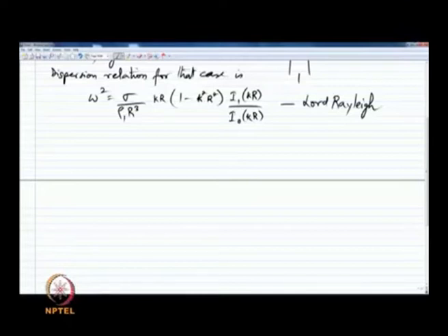And the source of this growth is essentially surface tension energy. A cylindrical jet that is infinitely long has greater interfacial energy in terms of the surface tension than liquid spheres that are discrete and arranged a spacing apart given by 2 pi by k bar in a non-dimensional way. So, this is the finding from the linear instability calculation, and this state overall has lower interfacial energy than the initial state, which is an infinite column of liquid.